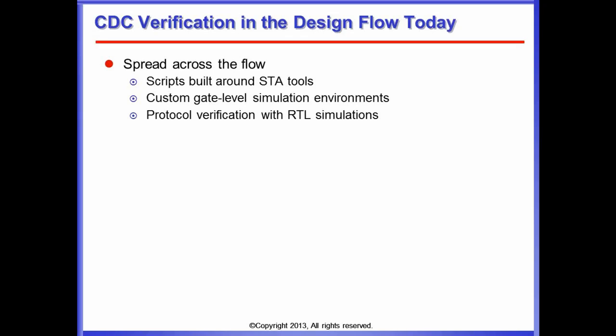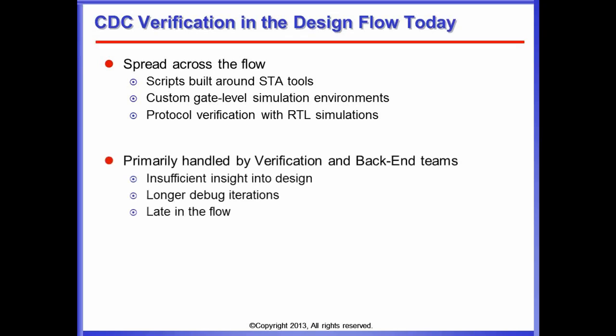Or this protocol design I showed you just before is checked just using RTL simulation. That leads to CDC checking in many cases happening after the implementation, where implementation, I call it synthesis. So you're working on the netlist, so it's done by the verification teams, by the backend teams. If a problem is detected, that leads to a longer iteration cycle because they have to go back to the designer to change the design and run through the implementation cycle again, and before that, of course, through all the RTL regressions they might have.